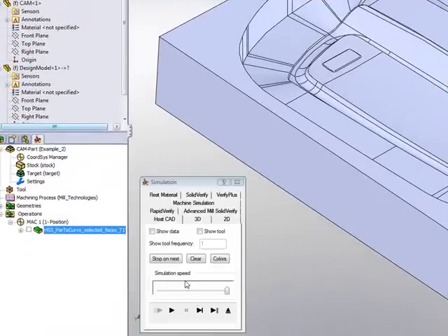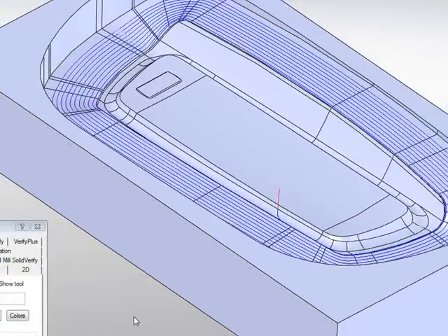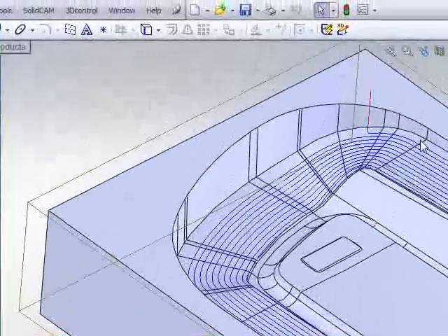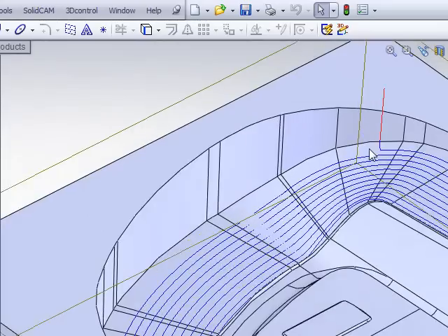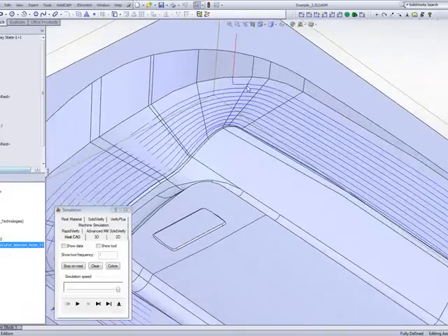and we look at our simulation, we'll see that the toolpath itself is going in a spiral fashion around the part itself. And let's take a look at you'll note that the toolpath stays 1 millimeter away from the wall itself. Not only that, we have our lead in and lead out. My lead in going in an arc as shown here vertically, and my lead out also going in an arc, but also leaving the surface going straight up by 1 millimeter.